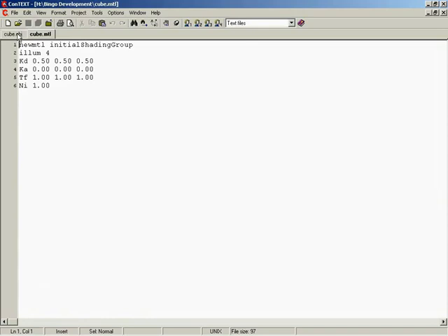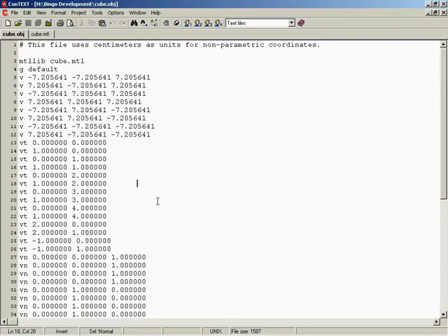Yes, it is. Now, let's jump back over to the OBJ. Joel, if you want, take us on a stroll through the format. At the very top, we have a # followed by a comment, so these lines are simply ignored. Then we get to our mtllib, which says which material library file we are associated with. And cube.mtl is what was exported along with it, so we know the association. And g specifies the group we're dealing with, the default group. At this point, it starts defining the vertices, the texture coordinates, and the normals.